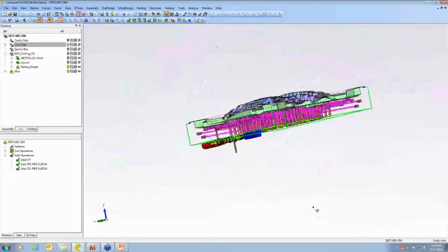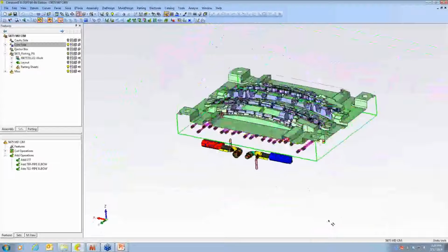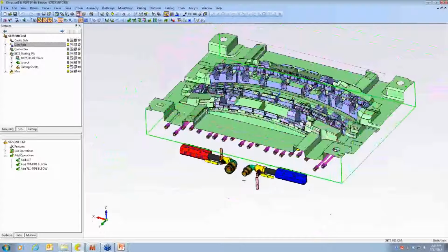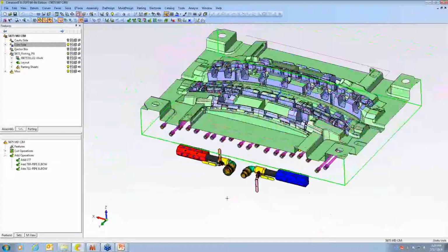Because of all the channels exiting the sides of the tool, a lot of external piping is used on molds like this. And these are all connected to water manifold assemblies bolted to the sides of the tool. So in this way, a large quantity of fresh water can be supplied, and all the heated water can be collected out.